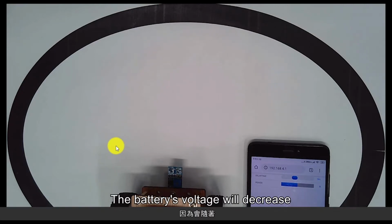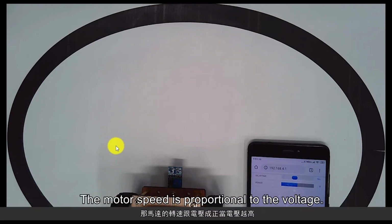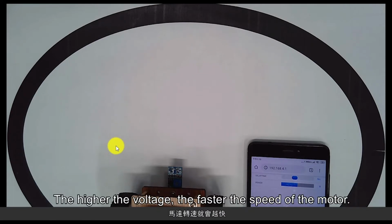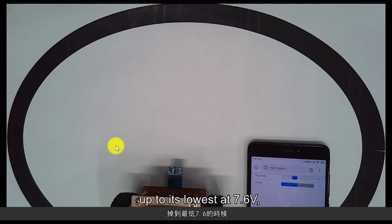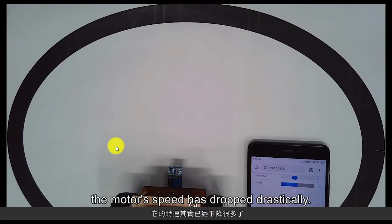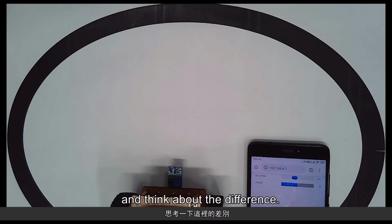The battery's voltage will decrease as operating time goes on. When the battery's voltage is just charged, and is 8.4 volts, the voltage is relatively higher. The motor speed is proportional to the voltage. The higher the voltage, the faster the speed of the motor, as your battery's voltage keeps dropping up to its lowest at 6.6 volts. Before charging the battery, the motor speed has dropped drastically. With a different rotational speed, the required delay time will also be affected. So you will need to pay attention to this setting and think about the difference.